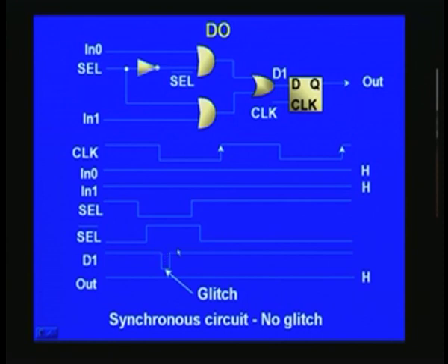The way to do it is to put the flip flop here. With a flip flop here, naturally you can rest assured that there are other flip flops from which other signals are coming, or it may even be asynchronous, in which case you cannot directly put it here, you need another flip flop and then only process other asynchronous inputs, which we will see in the later slides.